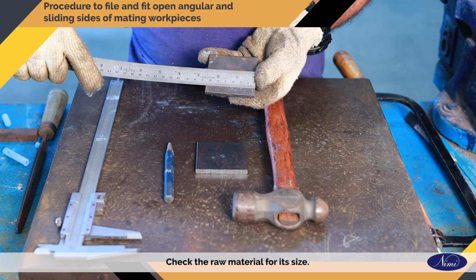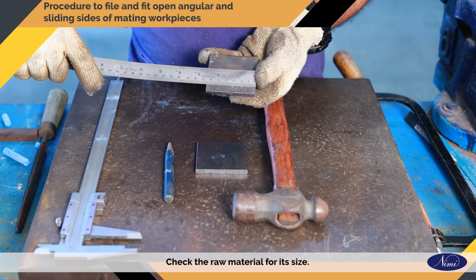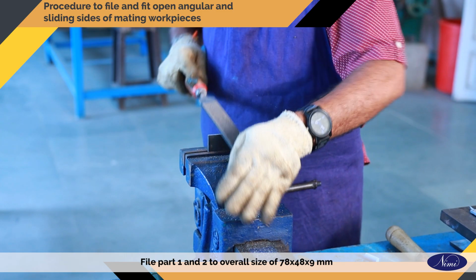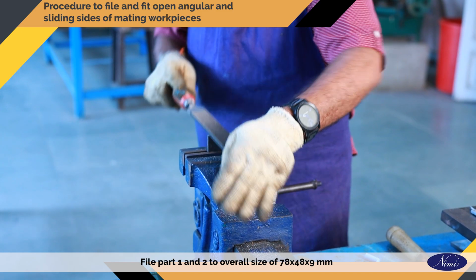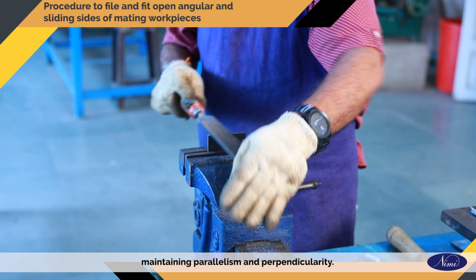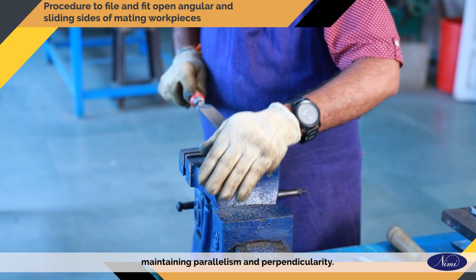Check the raw material for its size. File part 1 and 2 to overall size of 78 by 48 by 9 mm, maintaining parallelism and perpendicularity.